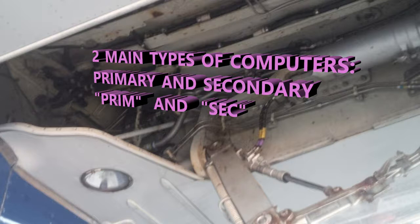Of course, all the computers that are going to be sending are connected to the actuators through the flight control remote modules and also the electronic modules. Those modules are essentially a translator in the signal processing field. They receive the digital signals coming from the computers and turn them into an analog signal for the actuators to move the control surfaces.